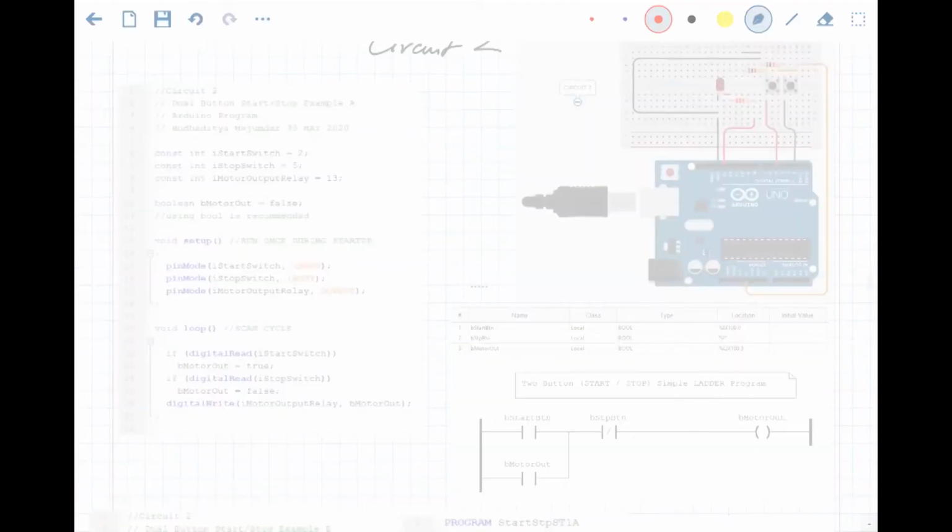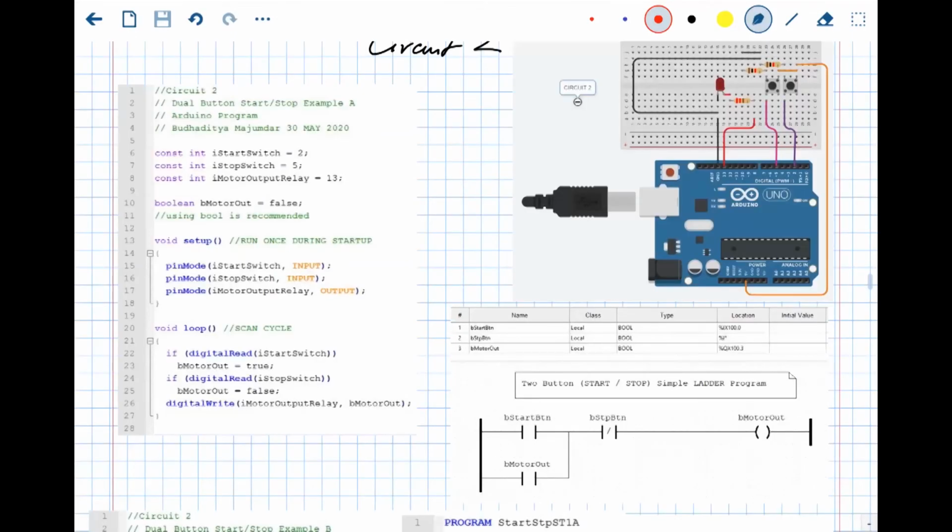On the other hand, in Arduino, it is not constantly synced in the program. You have to typically use a digital read function to read the hardware in every cycle. By default, it is not synced. One of the drawbacks is that this digital read function takes a lot of time to run and kind of slows things down. I think I saw that there are custom read functions which are much faster than digital read, and they are widely available over the internet. So if you are doing any project with Arduino that needs fast read, you can look there for code which does not use the digital read function.